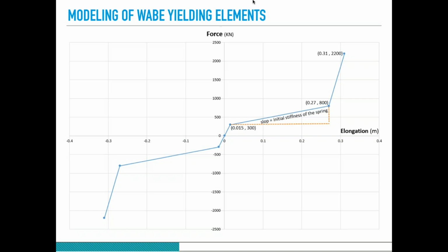But the fact is, in tunnel construction, when we have shotcrete, when it is fresh, it doesn't have a high stiffness. And when the force is applied on the tunnel, I prefer to transfer this force to the yielding element first instead of the shotcrete, so that I stop the shotcrete failure.